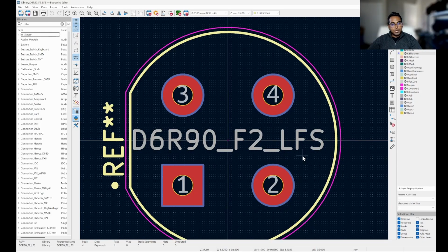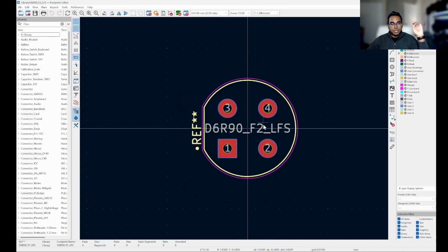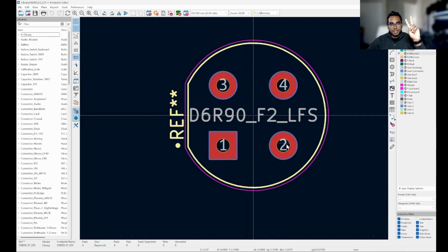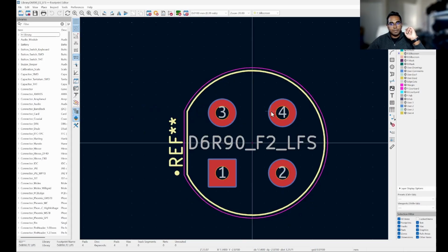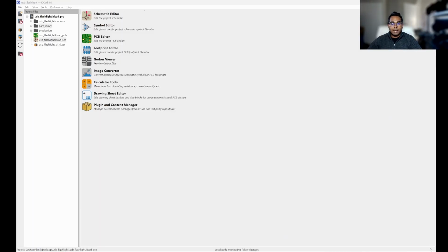So our switch, you know that most switches or buttons just have one input, one output. This switch, on the other hand, has 4 pins. So what it's actually doing is it's bridging together 2 pins as the input. So we can use either one of these, pins 1 and 2 for the input, and pins 3 and 4 are both the output. So I could just connect one of them, like I could connect an input to pin 1 and an output to pin 3, or I could connect to 1 and 2 for the input and pins 3 and 4 for the output. It doesn't matter.